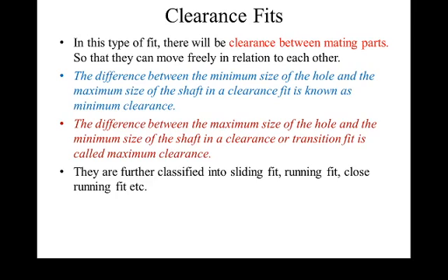Okay, now let us see each and every fit in detail. First of all we'll see the clearance fit. In a clearance fit, a gap will be available between shaft and hole. There are two basic terminologies for that, minimum clearance and maximum clearance. Minimum clearance is the difference between the minimum size of hole and maximum size of shaft, and maximum clearance is the difference between the maximum size of hole and minimum size of shaft.